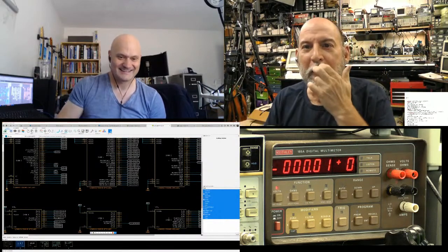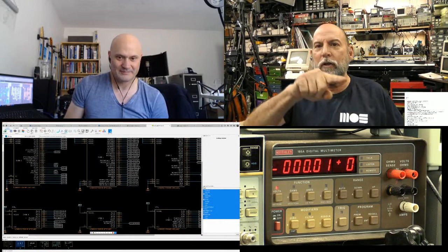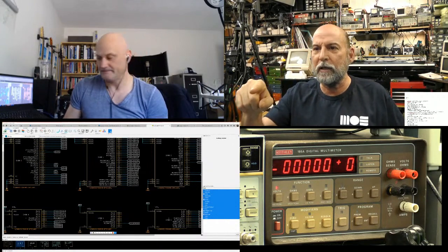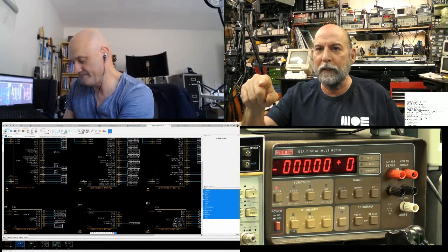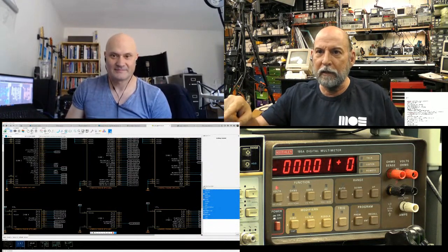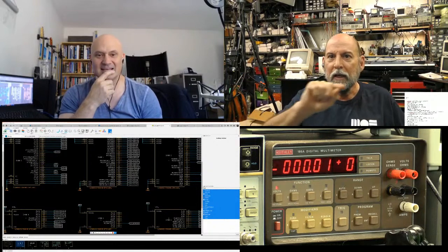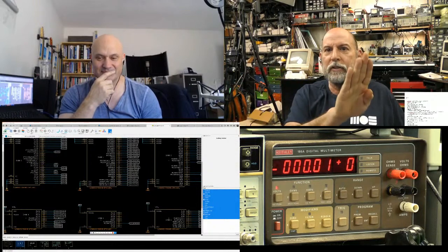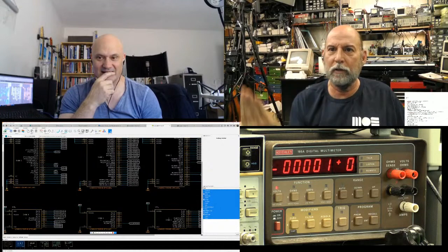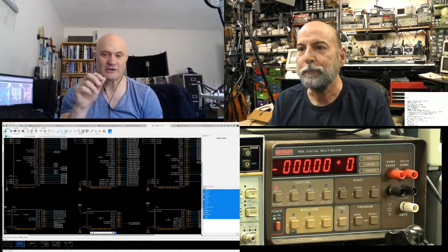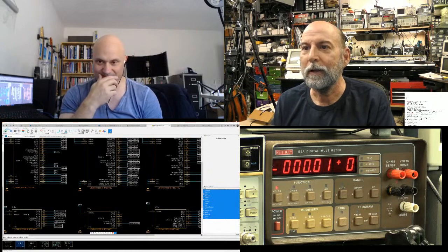I'd have to, but essentially, if you do a quarter of a sine wave, then you just clock it backwards, and there's your decrementing value, and then you invert the polarity, and now you're going negative, and then you invert the polarity and the clock, and it gives you the last tail. So a sine wave is the same portion folded and reversed. Yep. So it's pretty straightforward. So if you want to do DDS, that's how you do it.